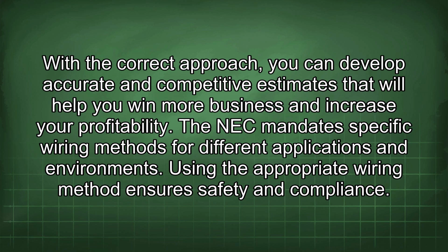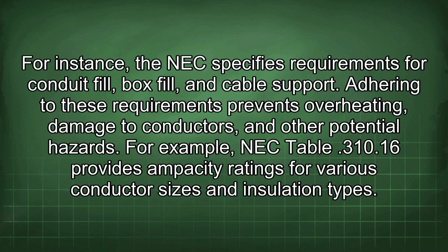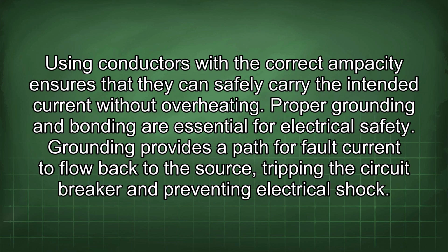The NEC mandates specific wiring methods for different applications and environments. Using the appropriate wiring method ensures safety and compliance. For instance, the NEC specifies requirements for conduit fill, box fill, and cable support. Adhering to these requirements prevents overheating, damage to conductors, and other potential hazards. For example, NEC Table 310.16 provides ampacity ratings for various conductor sizes and insulation types. Using conductors with the correct ampacity ensures that they can safely carry the intended current without overheating.